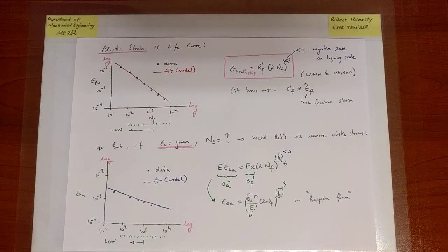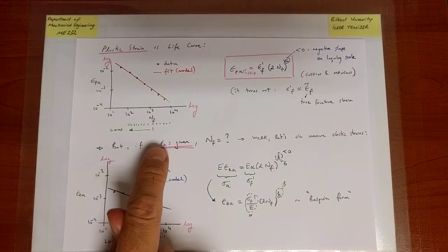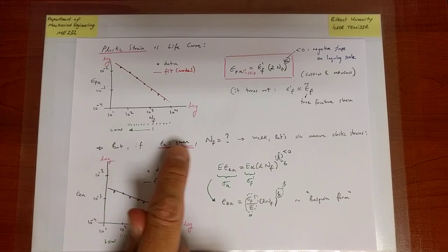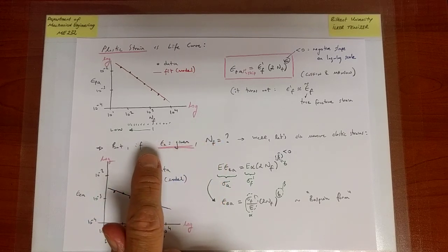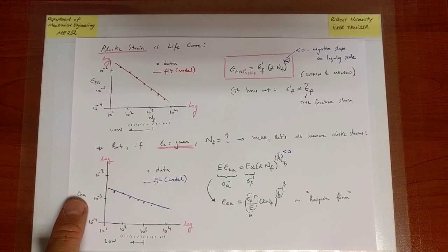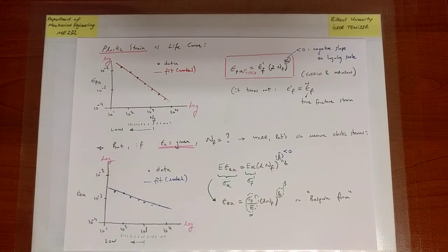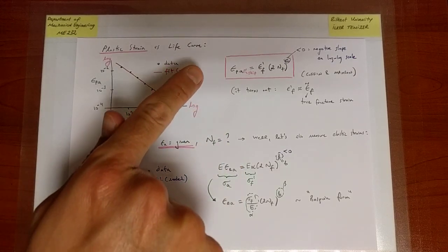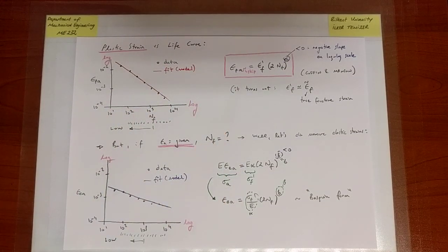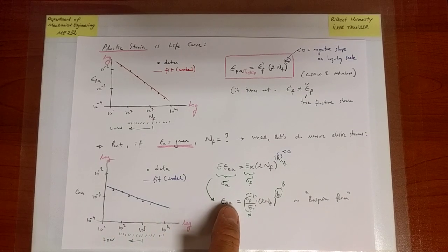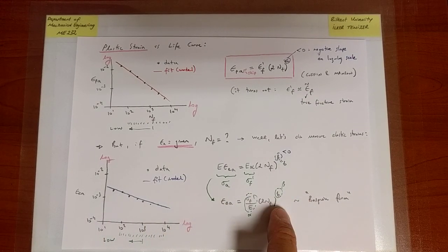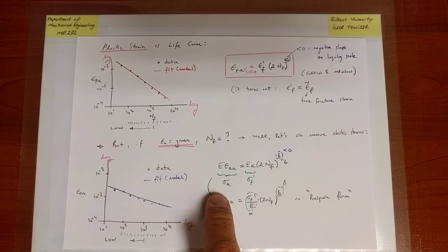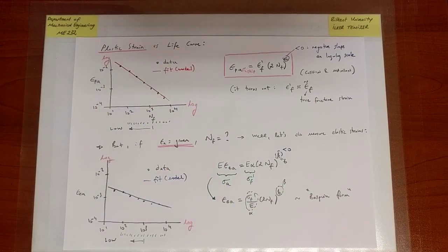We have observed, based on a strain amplitude driven experiment, a relation between the plastic and elastic components of the strain versus number of cycles to failure. Individually on a log-log scale, they seem to fit on a line, and therefore we fit them on a line explicitly, individually. One part of it is already in the Basquin form implicitly or indirectly. The other part is new to us, and it was proposed in the 1950s.